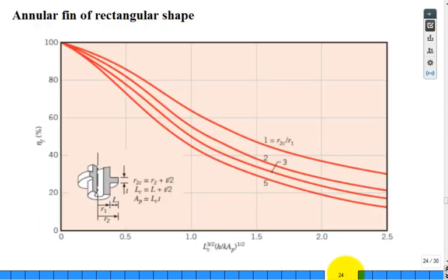All right. Well, not all fins are easy to analyze geometrically. Sometimes that cross-sectional area changes as a function of x. Here, for the pin and the rectangle, they were constant. But here, can you see that the area is changing as you come out for a round fin like that? So they have solved these things, and they put the fin efficiency as a function of a parameter